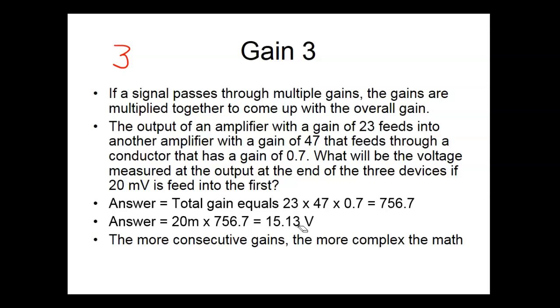You'll run into this in gear ratios. So out over in. You got a gear on the output that's got 1,000 teeth. You got a gear on the input that's got 50 teeth. Out over in, so the torque gain would be 1,000 divided by 50. That would give you the torque gain.